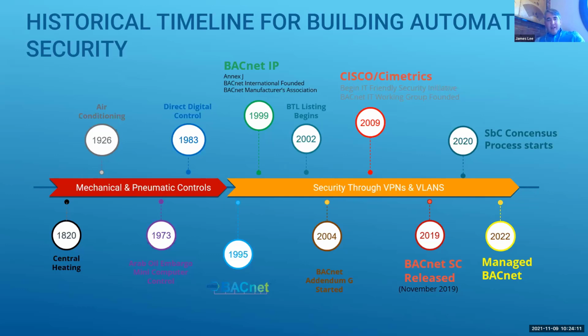By 1999, the BACnet committee innovates and introduces BACnet IP. Now, most building automation systems today are based on BACnet IP, at least at the management and larger controller level. And we're going from MSTP or twisted pair networks, the lower level of these architectures, to all IP connected devices fairly quickly now. Products to do that were introduced between 3 and 5 years ago by most manufacturers, and they're absolutely mainstream in the process today.